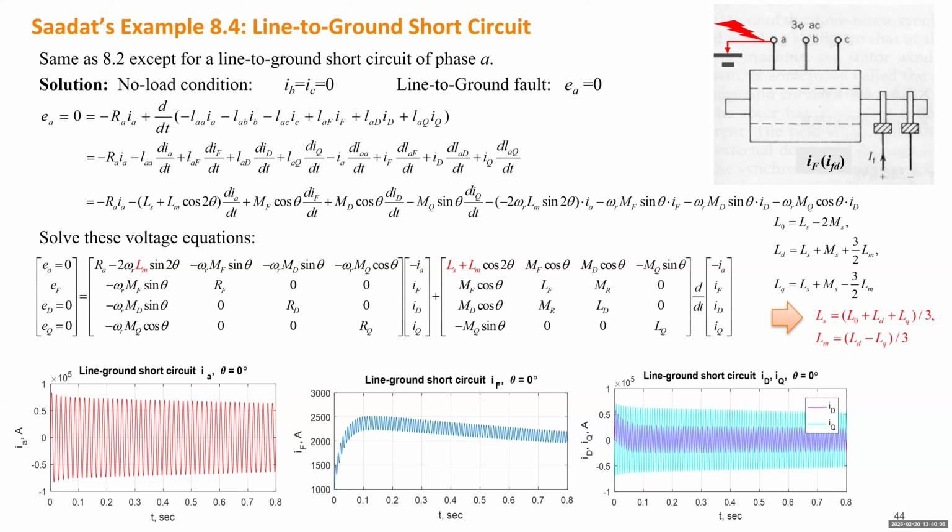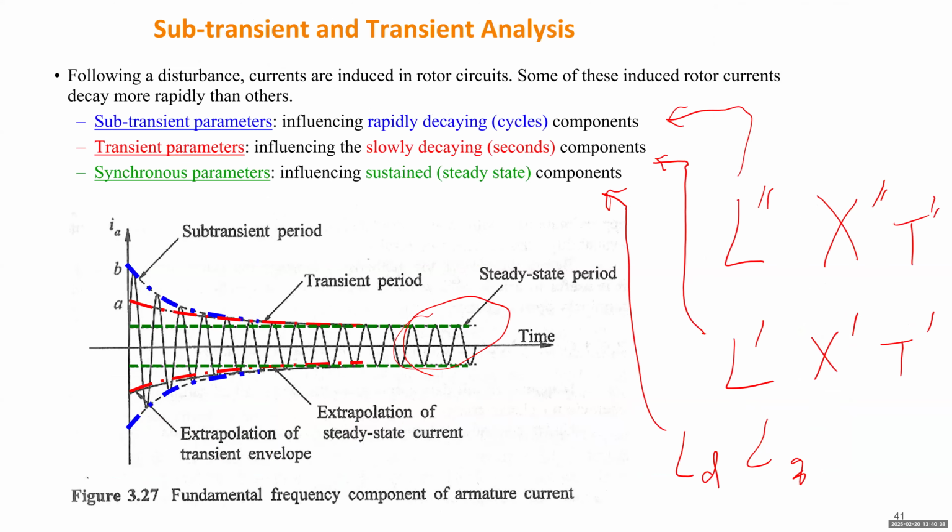Using our first model, we can accurately study any dynamics of the system, no matter whether it's a balanced fault or an unbalanced fault. But the problem is it is not very convenient. We don't want to integrate so many equations every time, no matter what dynamic we want to study. Then we need to think about how we can simplify the model. It will be very beneficial to categorize 3 types of dynamics, and come up with parameters categorizing each type of dynamic.